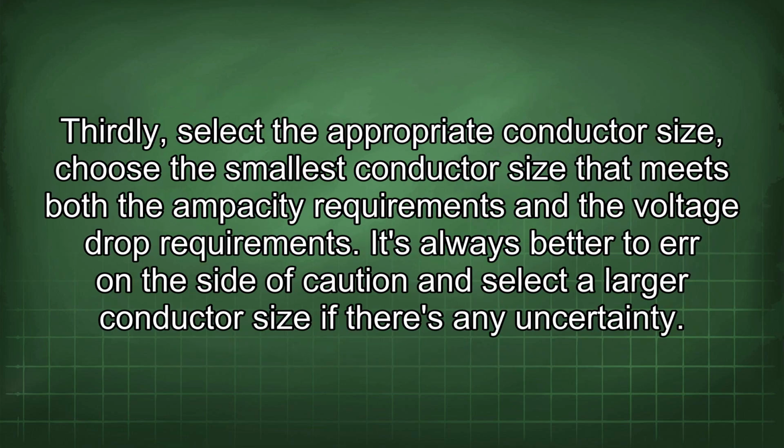Thirdly, select the appropriate conductor size. Choose the smallest conductor size that meets both the ampacity requirements and the voltage drop requirements. It's always better to err on the side of caution and select a larger conductor size if there's any uncertainty.